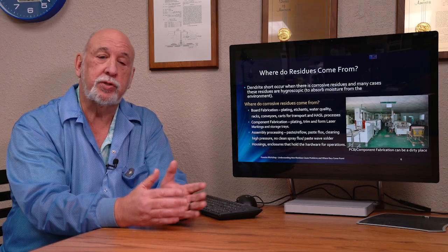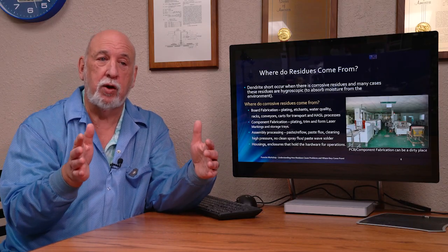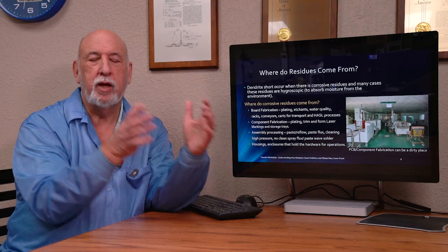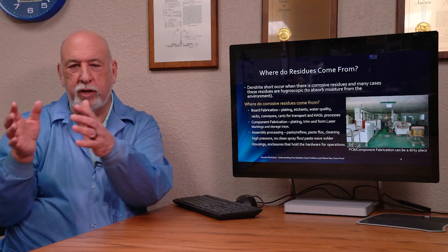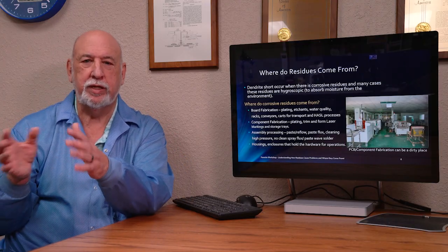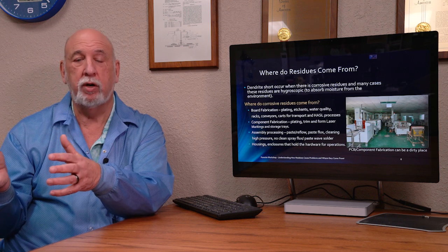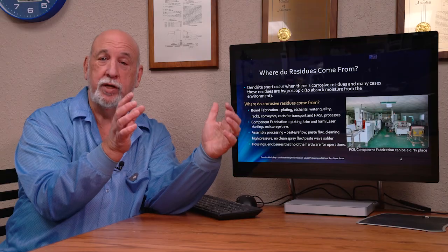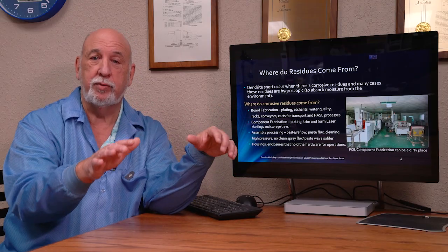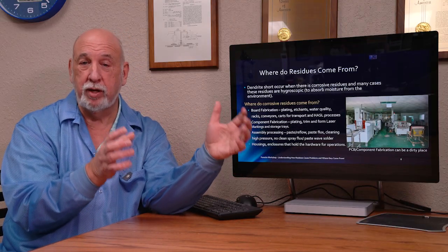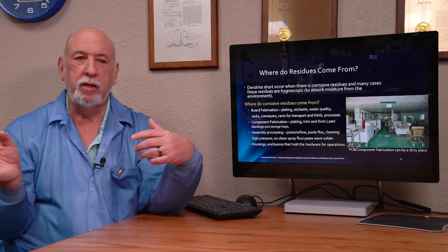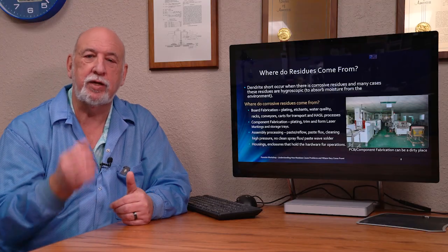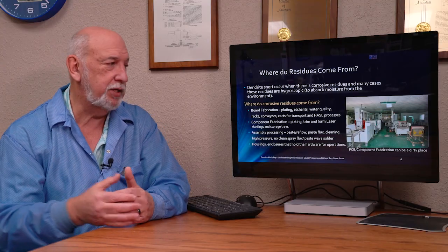A lot of times they use cascade forward systems that allow for dirtier water to be the first spray, and then less dirty water, and then the final rinse water is either RO or tap water. And so we get really dirty gray water that is the first thing that's on, hoping to rinse off some of the contaminants from the etching and plating processes. Sometimes it makes more contamination, and so there's a lot of rinsing that is needed post these processes.